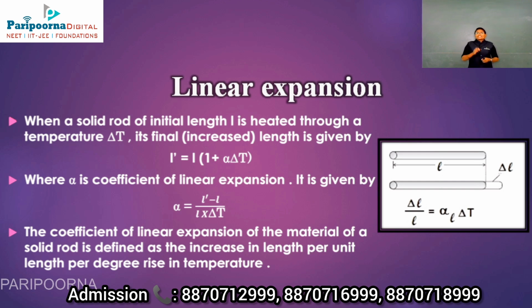Now here comes the linear expansion. When a solid rod of an initial length L is heated through a temperature del T, its final length is given by L dash is equal to L into 1 plus alpha del T, where alpha is the coefficient of linear expansion.